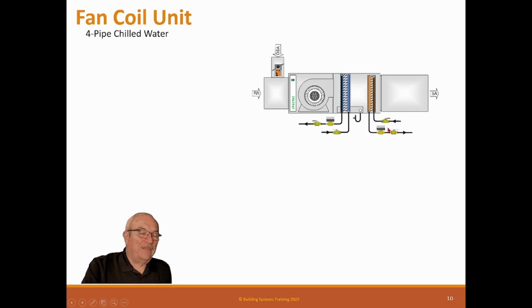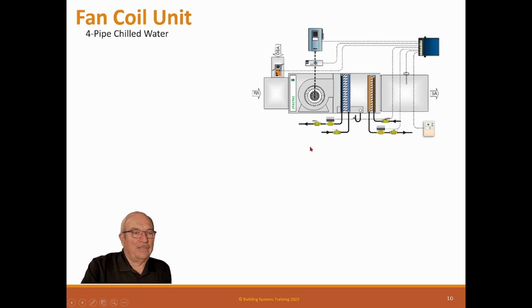That's pretty simple. However, you need to understand that the definition of 4-pipe is more than 2-pipe, not actually 4 pipes. Because you could have a system with four coils, and then you would have 8-pipe, but it's not called an 8-pipe. It's called a 4-pipe unit. So just that little interesting thing there.